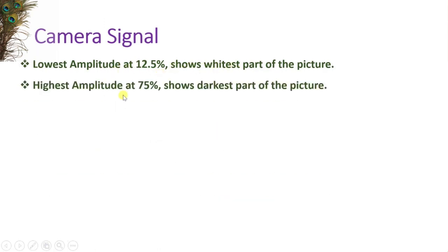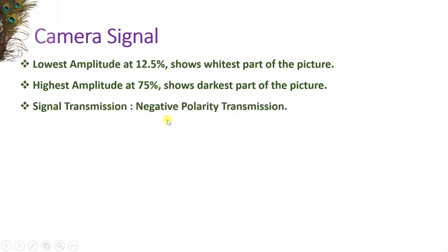The part immediately before the sync pulse is called the front porch, and the back porch follows the sync pulse. The width of the front porch is 0.02 H. This time period is 1.27 microseconds for the front porch and 3.81 microseconds for the back porch. Note that the back porch is 3 times longer than the front porch. All time periods within a horizontal line are summarized in Table 7.1, with the necessary tolerances. Figure 7.6. Details of horizontal blanking and sync pulses.